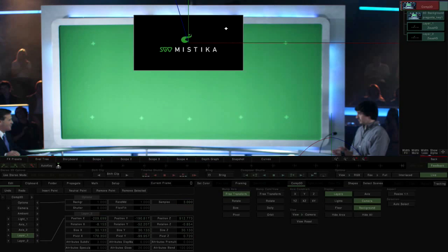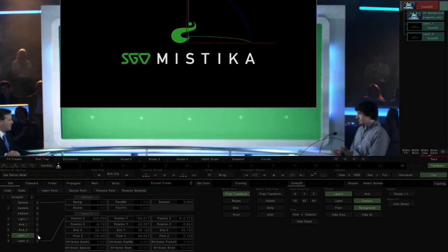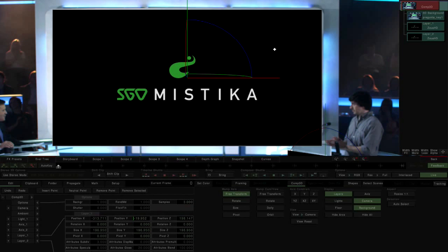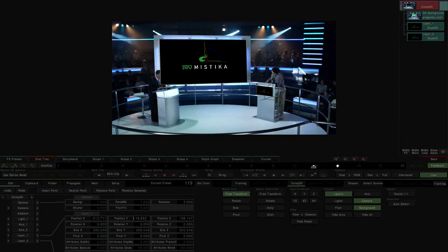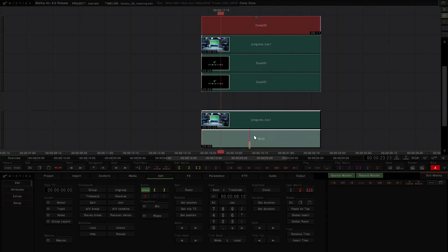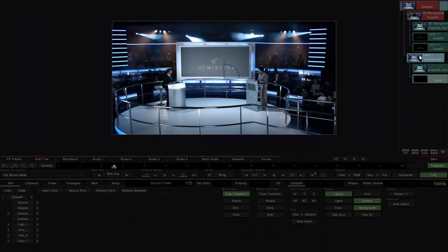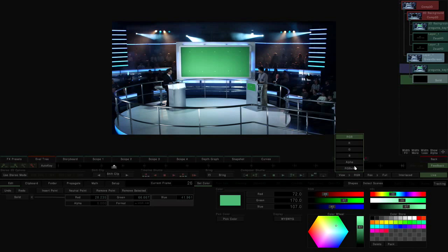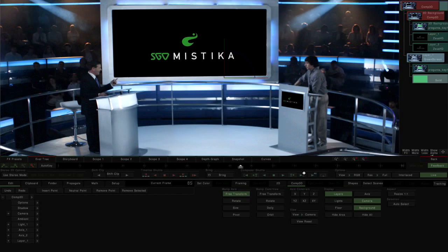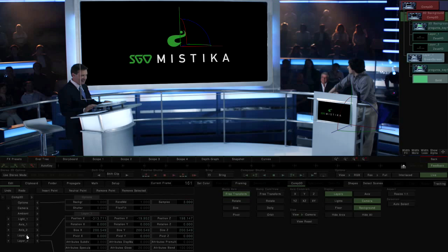There won't be so many problems with the larger screen, since the pivot point is in the center and the screen is virtually front-on to the camera. We can see that both screens are located and scaled correctly. We'll compose the original image on top of this tracking, carrying out a quick mask with a combination of the green screen and solid effects. Then we end by adjusting the position of each screen manually.